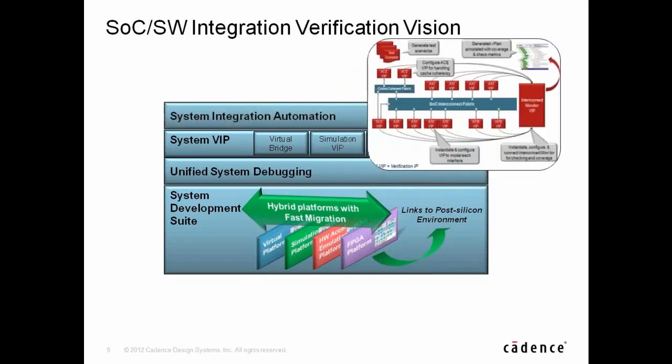One of the products, as I said, I'm responsible for is really starting to look at automating the creation of test benches. Test benches at the SoC level are a nightmare because you've got potentially so many interfaces, and you may want different incarnations of them. If the SoC architecture changes, I'm now going to change my test bench. Well, it's much nicer if you automatically generate a test bench, and one of the products I'm responsible for is something called the Interconnect Workbench, which will take IP-XACT and generate a test bench automatically for interconnect infrastructure.